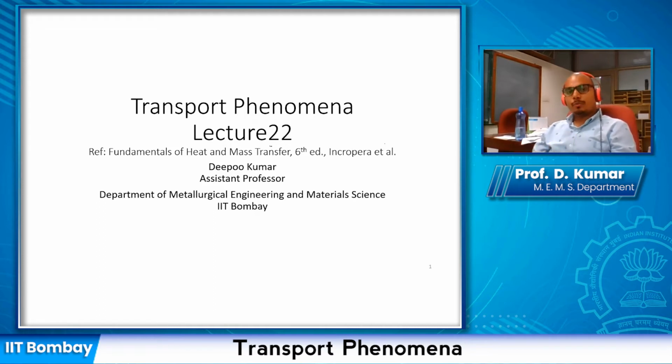In addition, you also have to be aware of the flow behavior. Some correlations you can only use for laminar flow, some correlations you may use for turbulent flow, and so on. Another aspect is that very often we want to know the average convection heat transfer coefficient, and because of boundary layer development, we have seen that the convection heat transfer coefficient varies significantly with the spatial coordinate.